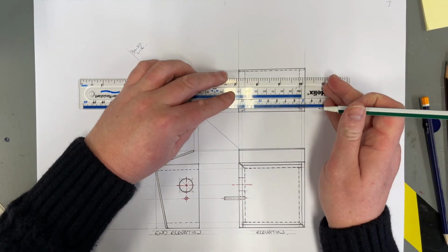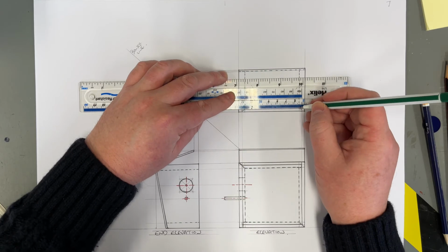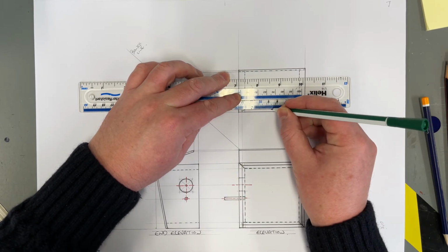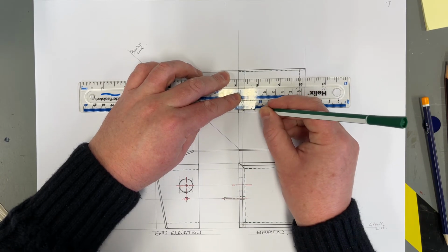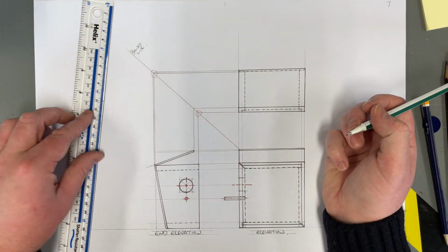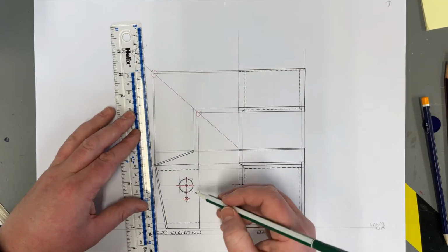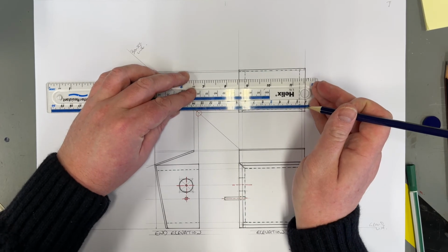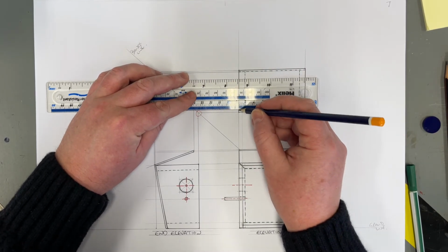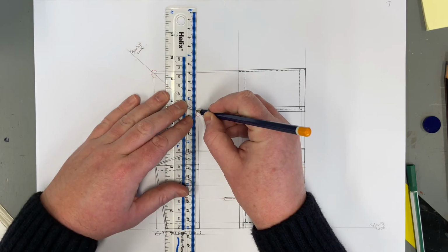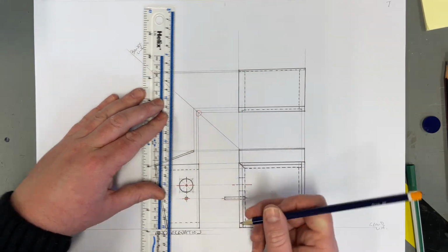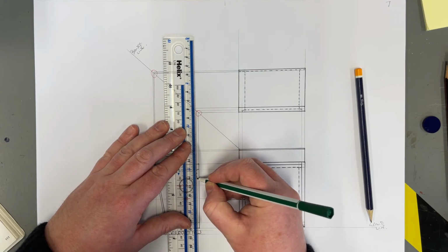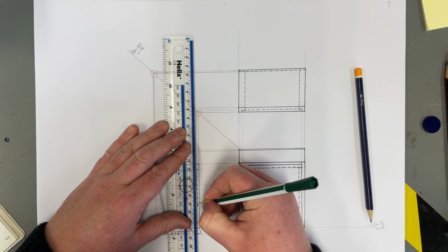And then obviously the plastic itself, we know that it's flush to the front, so it would have a thickness. We've got that little line, and we're just going to put hidden detail in there too, to show where the plastic would go. We haven't quite done that on this view here, so what we could do is take the thickness of the plastic, project that back the way, from this point, back down to the end elevation, and we know that the plastic would slot in something like this.